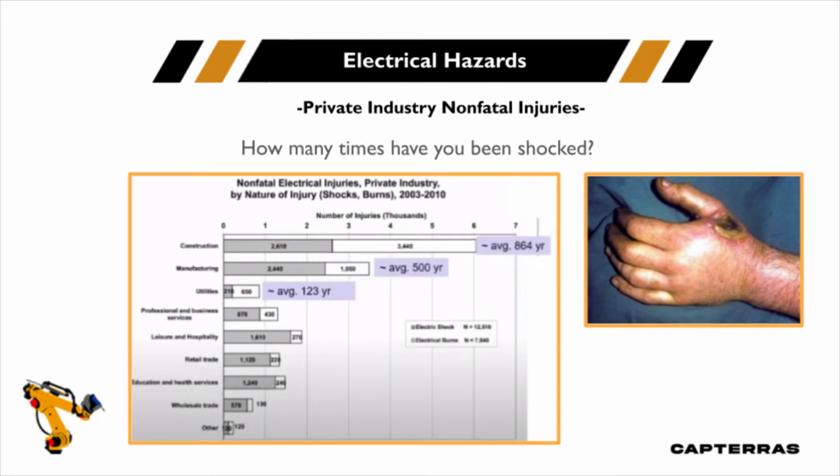When we look at the hand in the upper right of this picture, we can see that this is actually from an electrical contact burn. This gentleman reached into a junction box to pull some wires out, and next thing you know, he can't move, he can't say anything. He is stuck there on the electrical circuit. What happened is the wire was stripped too far back. It was sticking out of the wire nut or wire connector, and he was lying across metal. So what started out as a small pinhole in his skin ended up, over the next week or so, looking like this on his hand. It actually cooked his hand. In other words, the electricity flowing through it cooked part of his hand.